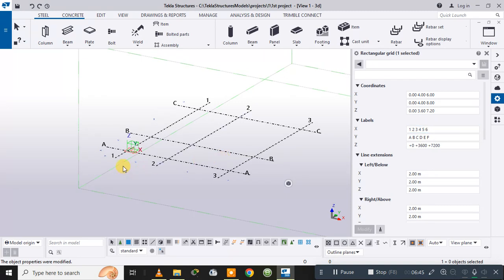And in the labels you can see here 1, 2 and 3 are present. So simply remove the other labels. And similarly here A, B, C. So remove the others. Accordingly, now keep the height of the building as 3 meter, then the second height as 6 meter.